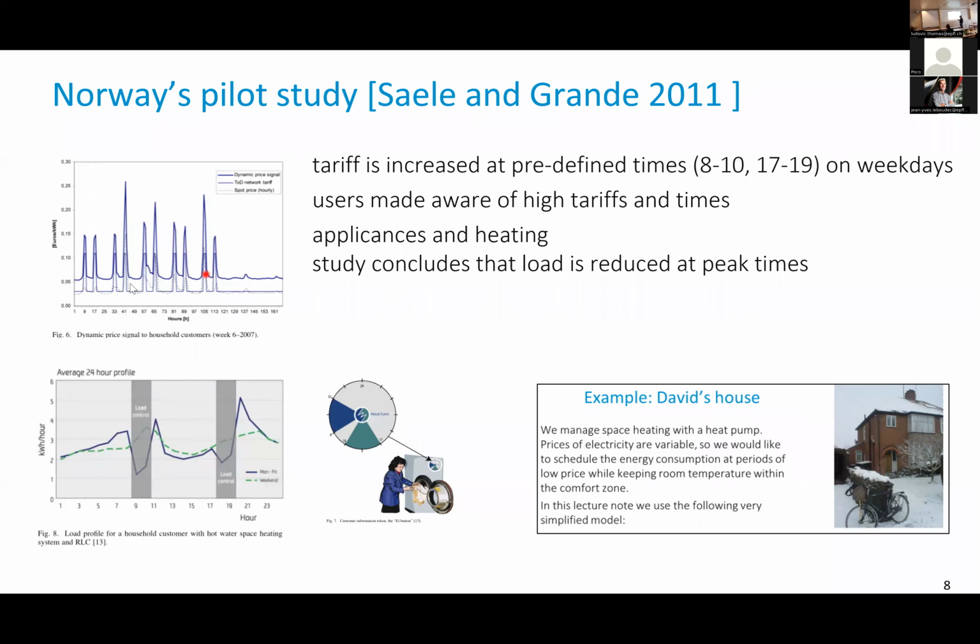So that has happened exactly in Norway. So very high prices have resulted, or larger prices have resulted, in some parts of the country. To mitigate this, they introduced a demand response program where they advertise hours ahead of time hours of the day, which here are the morning peak and the evening peak, the Norwegian morning and the Norwegian evening.